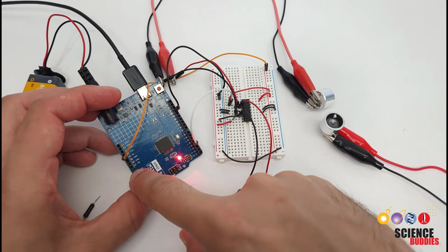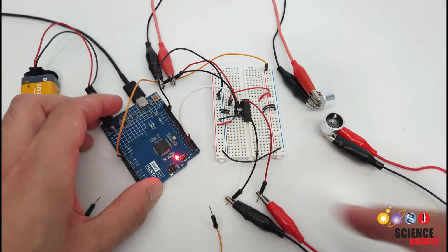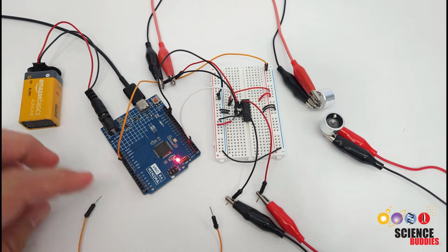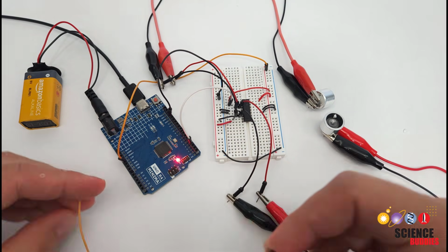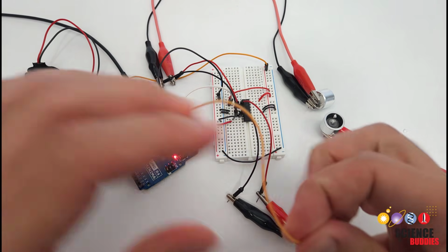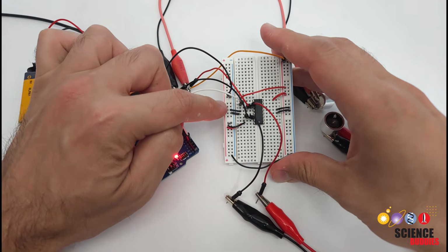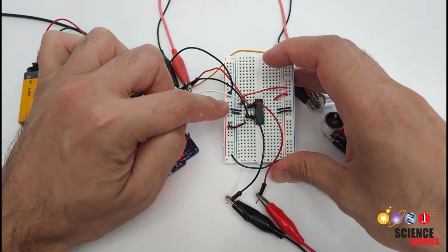But on the Arduino here, we have a V-in pin, and that is going to provide the raw voltage from your power supply. So what I can do is take a jumper wire, plug one end into the V-in pin, and the other end into the power bus on the left side of the breadboard, which you remember from Tinkercad we had left unconnected before.